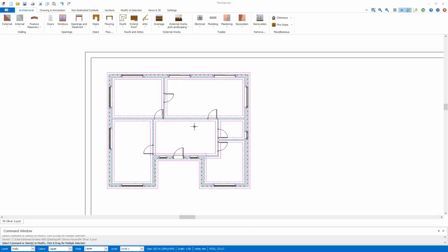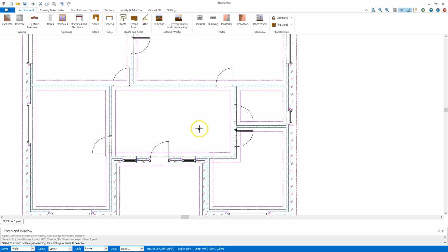In this section I shall be taking a look at placing these stairs. Before we place the stairs I want to consider their positioning and make sure it's easy to place my floor later on. To do so I'm going to make sure that I'm able to put a trimmer from here to here, and to make sure I can line that up I'm going to use a construction line.